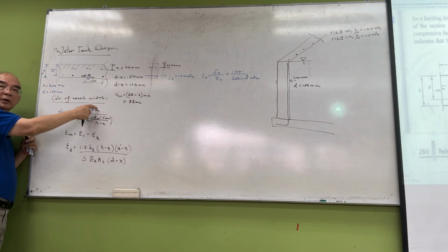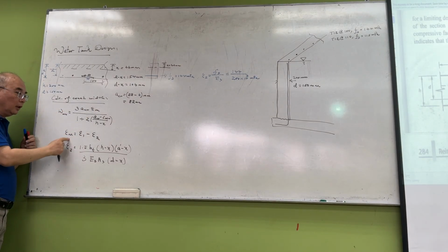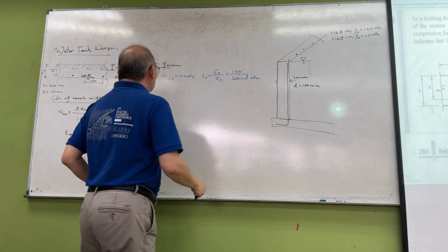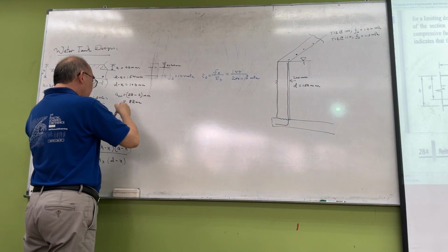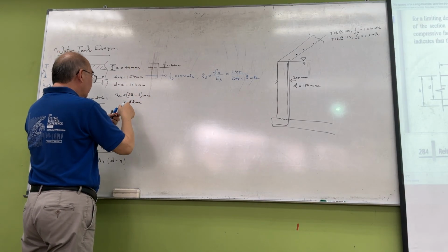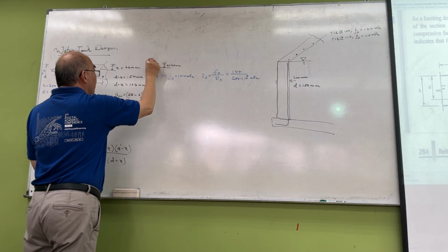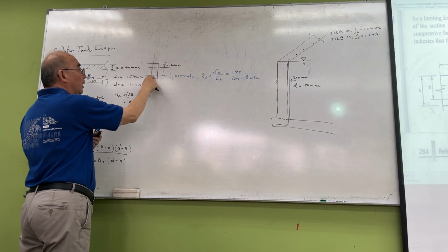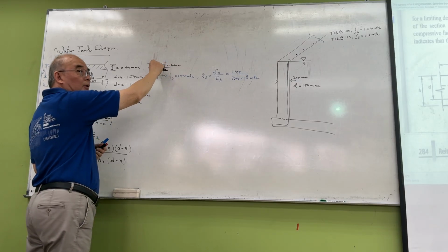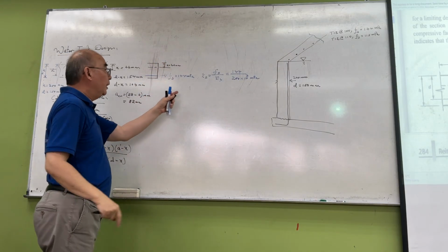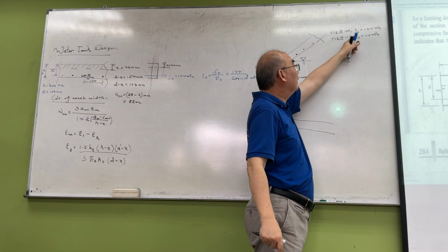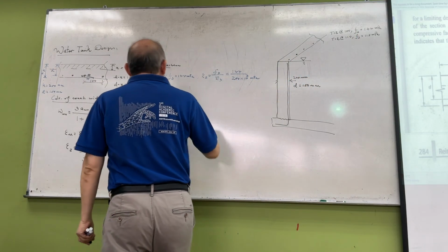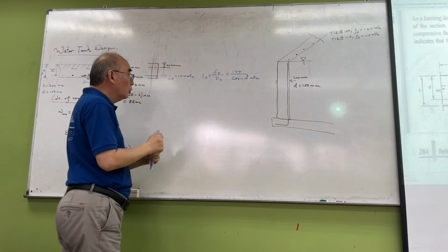So we need the epsilon m. Epsilon m is equal to epsilon 1 plus epsilon 2. How do we calculate epsilon m? This is the side view of the slab. So this is the rebar, and this is the X. Now, based on the T12 at 150, our rebar stress is 144 MPa.